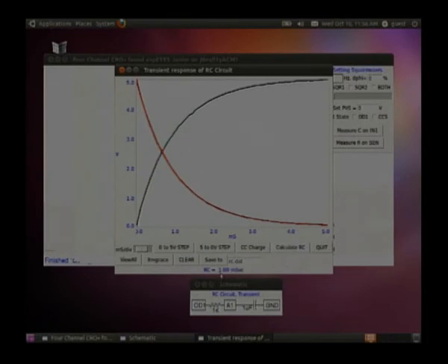It says it is 1 millisecond, that means 1 kilo ohm and 1 microfarad is 1 millisecond. So, you can use this experiment to measure the value of a capacitor. All you have to do is use a resistance of known value and extract the RC time constant, the product of RC, from the graph.